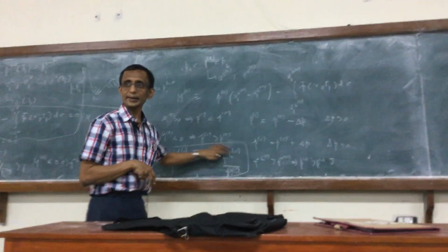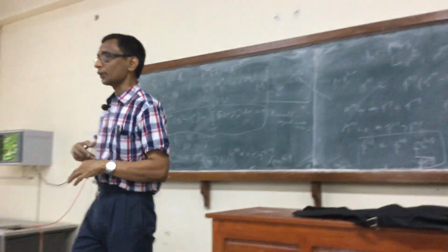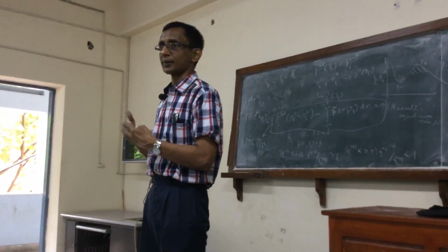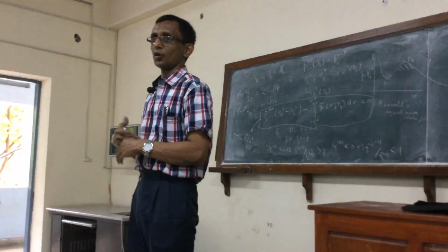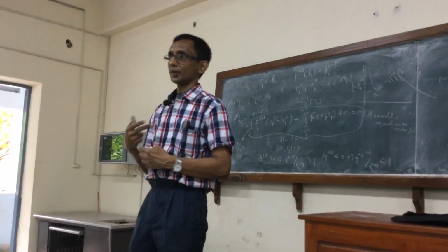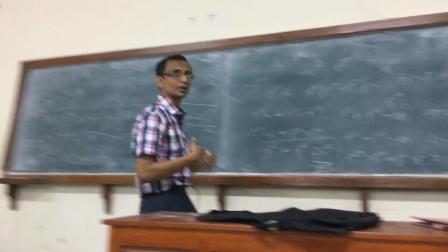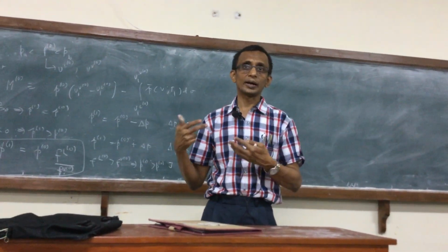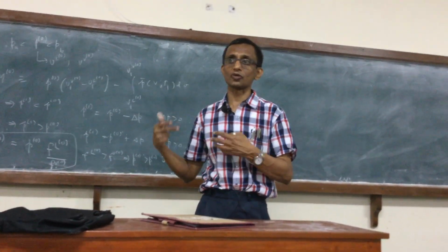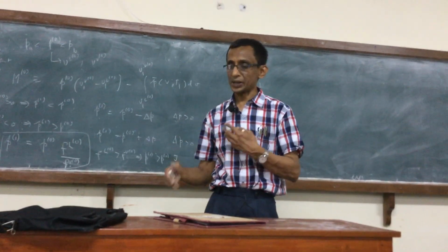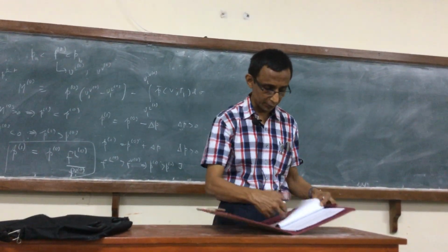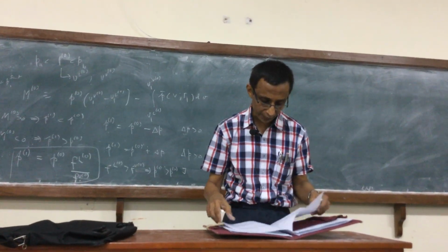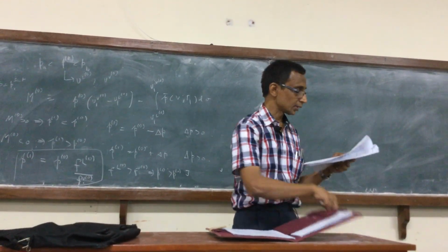But however, this idea is useful stated in terms of fugacity, right? Because you see that the pressure scales as the ratio of the fugacities, right? Pressure for the next iteration, the ratio of that to that, and that makes sense because pressure has the same units as fugacity, and you can use this as a good way to scale the pressure. So if I want to write this whole algorithm in terms of M, which is what we are going to calculate, I can simply write this as, I'll just copy it.